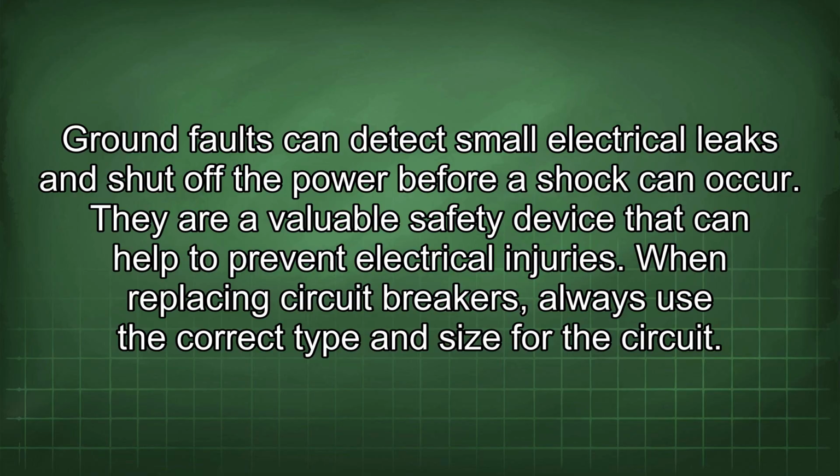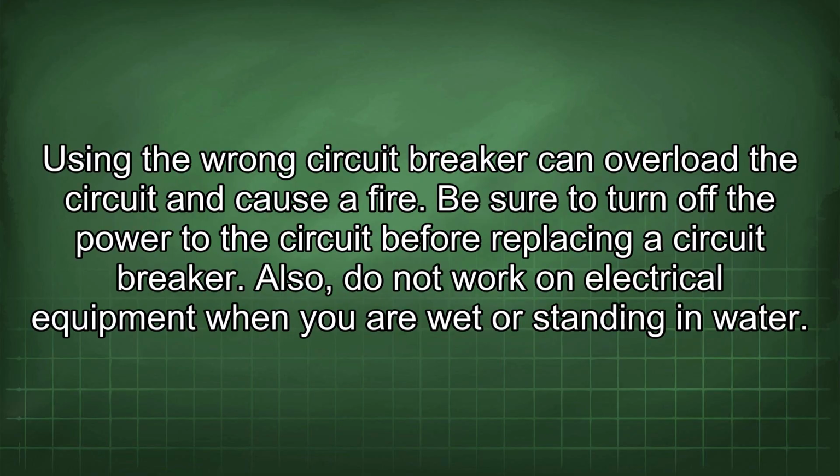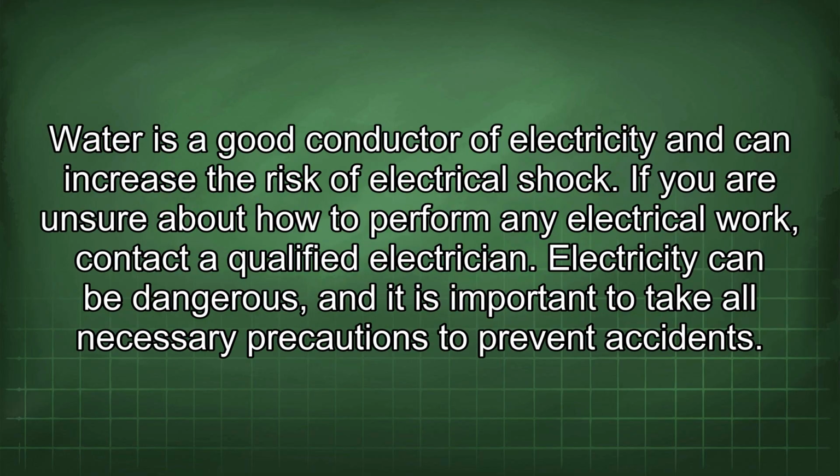When replacing circuit breakers, always use the correct type and size for the circuit. Using the wrong circuit breaker can overload the circuit and cause a fire. Be sure to turn off the power to the circuit before replacing a circuit breaker. Also, do not work on electrical equipment when you are wet or standing in water. Water is a good conductor of electricity and can increase the risk of electrical shock. If you are unsure about how to perform any electrical work, contact a qualified electrician. Electricity can be dangerous, and it is important to take all necessary precautions to prevent accidents.